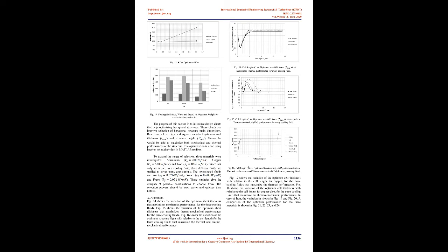The implication of figure 9 is that for designing thin cores, panels with triangular cells, with 6-point crossing point, outflank every single other structure, as a result of their modified load-bearing attributes. The situation changes for thicker structures. The hexagonal cells outflank all others in view of their superior thermal performance.